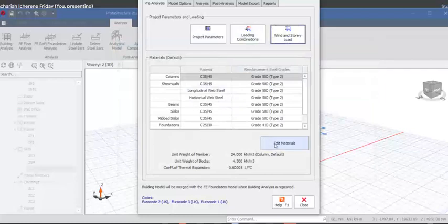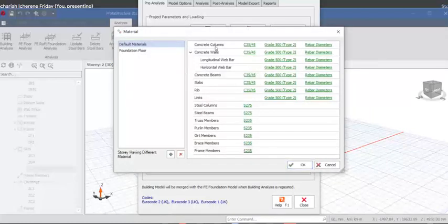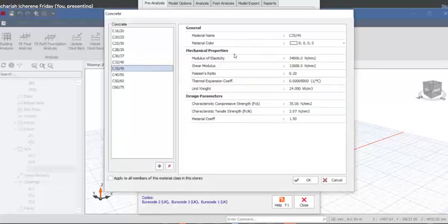The next thing you do is edit material. So for the reinforced concrete column you have in the structures, you have the grade of concrete to be used. You can use C20/25, okay, which is for the mix ratio of 1:1.5:3 right there. Okay, this is a normal mix ratio, it's not standard. I think standard mix ratio starts from 30, right, and then we have high strength grade. Okay, so you can choose that one and then apply it to all. Click on the OK option right there.